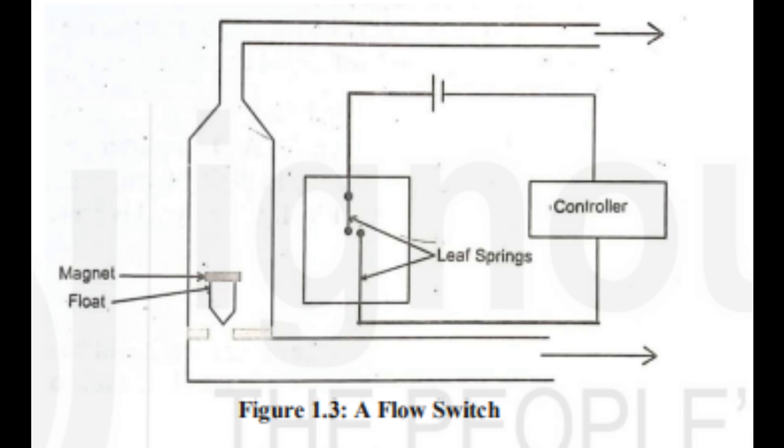1.5 Continuous sensor. The term continuous sensor is used to describe a device that converts one measured physical quantity into another that is proportional to the measured physical quantity. The measured physical quantity might be position, velocity, or temperature. The converted physical quantity is typically one that can be used in an electronic circuit, such as electrical resistance.